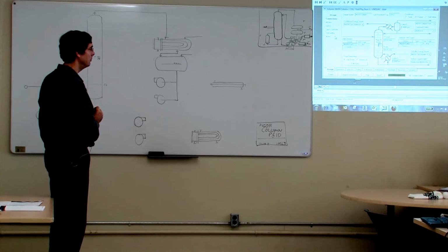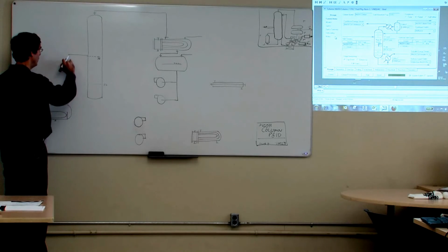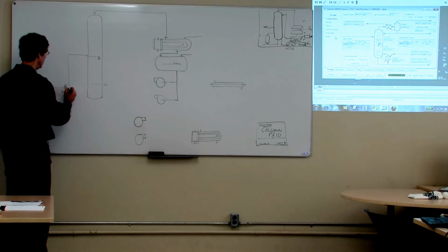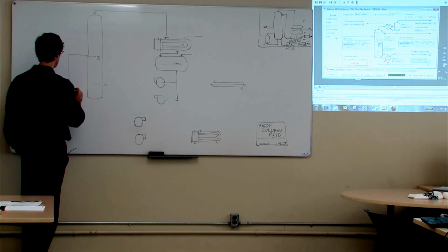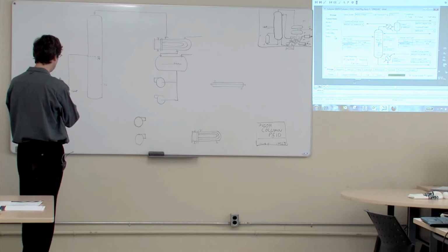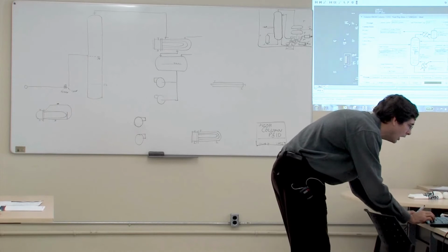Now what I've done by doing that, I'm thinking about this, is I have now put a two-phase flow mixture into this line. This is operating on the upstream side of this valve at 75 bar. On the downstream side of that valve it is operating at 2 bar plus my static head and all the pressure drops you guys did during the simulation rationalization. So I'm just going to guess that it's about 4 bar, just an approximation. Okay, so I know I'm going to have some two-phase flow there. I might go to the model and just check what I've got.